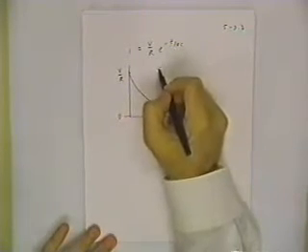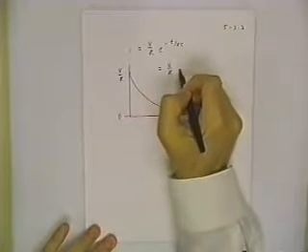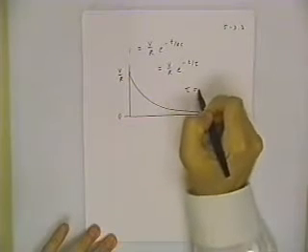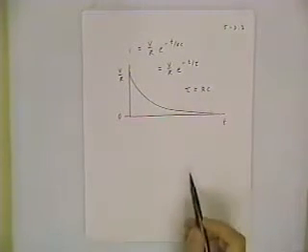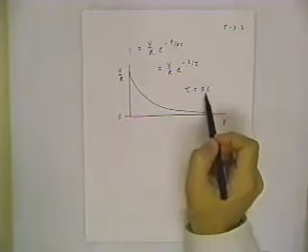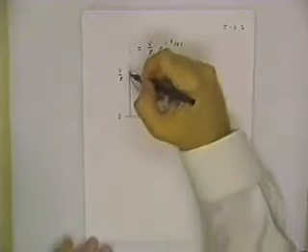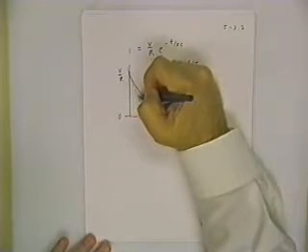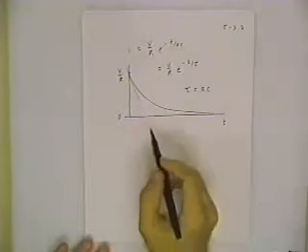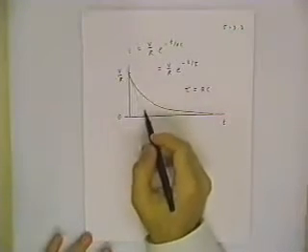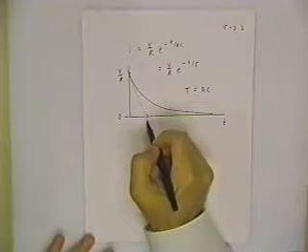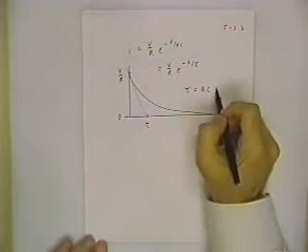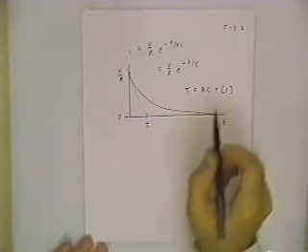And in the meantime, it's going to follow an exponential decay shape. Another way of writing this expression is to say it's some initial value V over R times e to the minus t over tau, and tau is called a time constant. One of the neater interpretations of the time constant is that if you look at the initial slope of this curve and just draw a tangent and continue at that rate, at a constant rate equal to the initial rate of decay, then your entire current would decay away in tau seconds. So that's a nice interpretation. Tau has SI units of seconds.